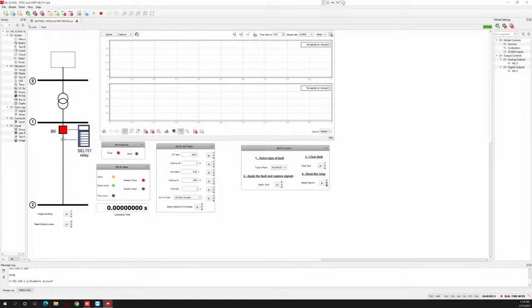And the second device here is also a clock, but this is a PMU. This is probably the second or third generation of PMU. This is a phasor measurement unit. This device is capturing measurements, phasors like this, of these voltages and currents, okay?